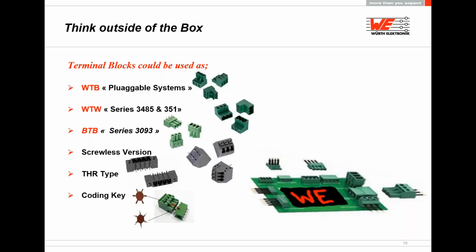Also, coding key. If it's an industrial board, I saw a lot of boards that have multiple right angle headers, with 8 positions or 6 positions as an example, and pretty much the engineer is just afraid of what could happen in the field, that the technician could mix and match plugs and make a short circuit on the board by plugging a wrong plug into the header.